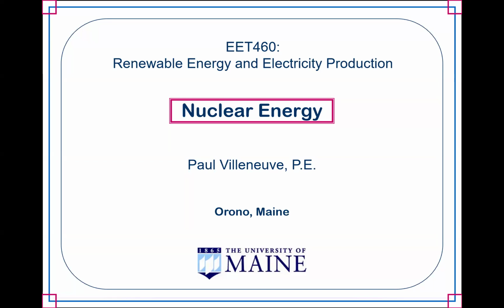Whereas with renewables, for example solar or wind, that is highly dependent on the weather. If it's a cloudy day or a very sunny day, the output from a PV array can be very different. Similarly, you have windy days or non-windy days with wind farms. So it's really more difficult when you have to include the weather, and it can make dispatching a very difficult process.